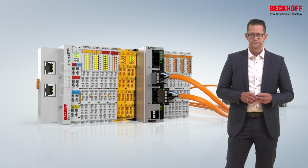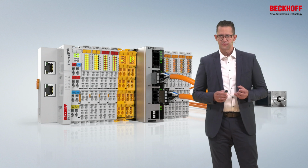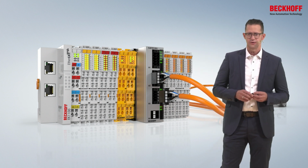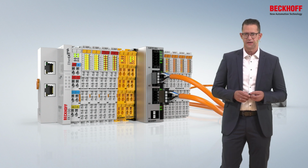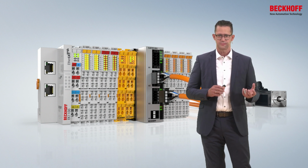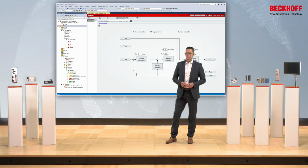the control quality. For simple point-to-point movements, all drive solutions support an integrated travel distance control. Here the drive controller receives all the values required for a movement from the application program via the process data. That means all necessary data for this travel command is transferred to the drive controller via the process data from the application program. This includes the target position, the speed and the ramps.